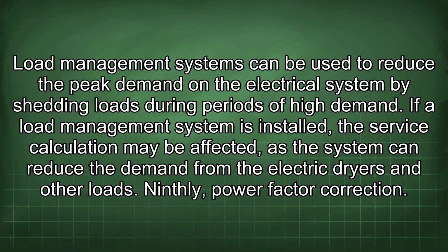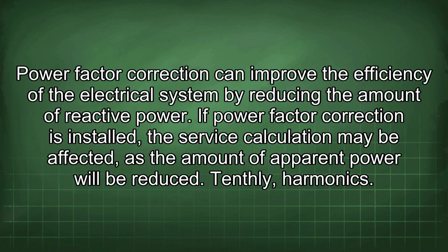Ninthly, power factor correction. Power factor correction can improve the efficiency of the electrical system by reducing the amount of reactive power. If power factor correction is installed, the service calculation may be affected, as the amount of apparent power will be reduced. Tenthly, harmonics.